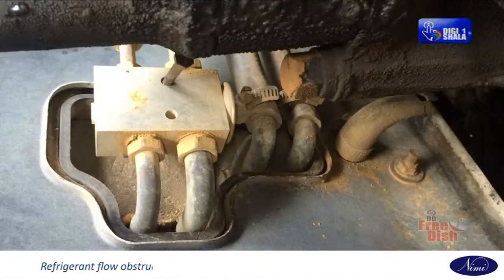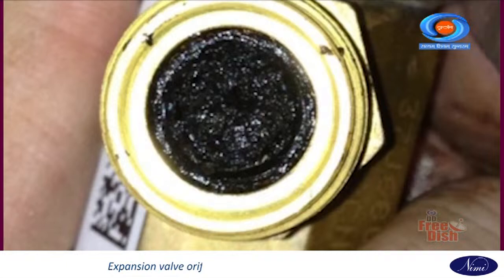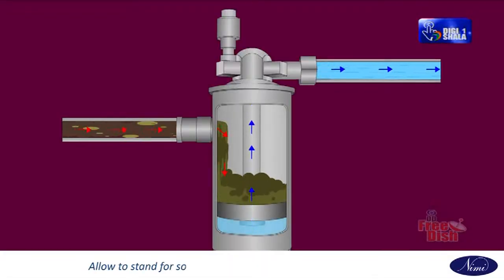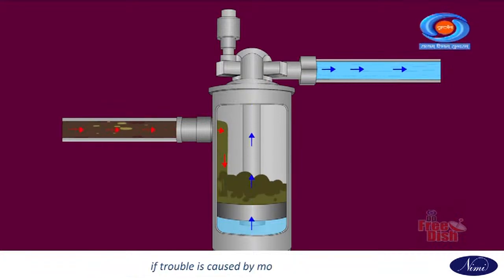Refrigerant flow obstructed by gas leakage from the expansion valve heat sensing tube. Diagnosis: expansion valve orifice clogged. Refrigerant does not flow. Remedy: allow to stand for some time and then restart operation to determine if the trouble is caused by moisture or dirt.